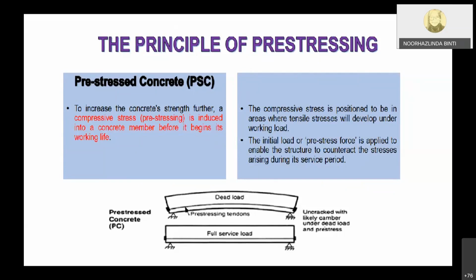The reason we introduce the initial compressive stress inside this concrete is for it to counteract the stresses developed by the service load, the live load of course, during the service period. So that's prestressed concrete. We are talking about how to tackle the problems of tension in this concrete.